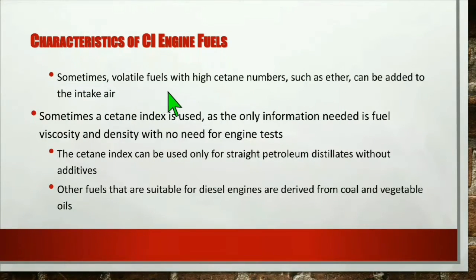Sometimes volatile fuels with high cetane numbers such as ether can be added to the intake air. Sometimes a cetane index is used, as the only information needed is fuel viscosity and density, with no need for engine tests. The cetane index can be used only for straight petroleum distillates without additives. Other fuels that are suitable for diesel engines are derived from coal and vegetable oils.